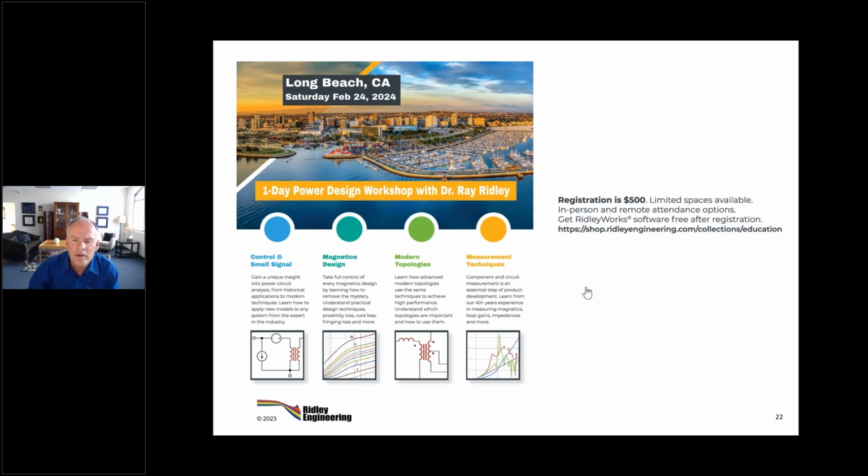Why are the losses increasing with the speed of changing B? Is this not switching frequency? Yeah, we're increasing with changing switching frequencies. But I think if you look on the curve, you'll see that losses decrease with frequency and increase as the frequency goes down. Now, the AC resistance, of course, is climbing with frequency. That's just proximity loss, and that's the gap loss.